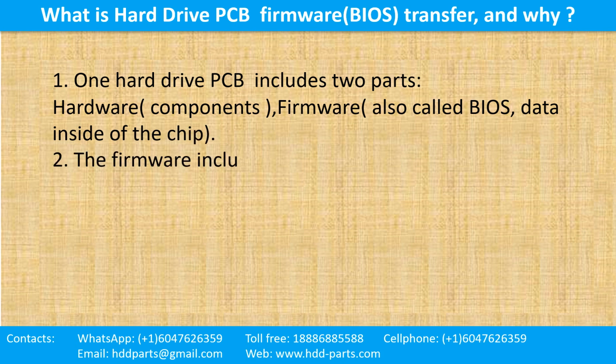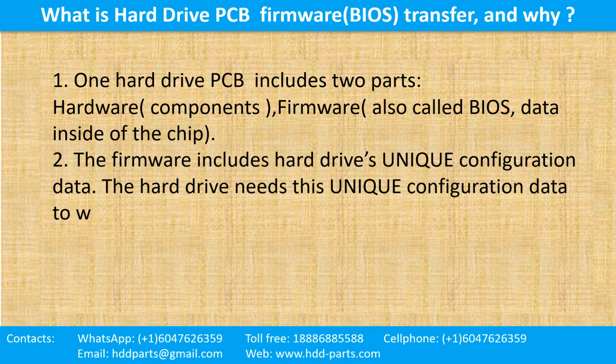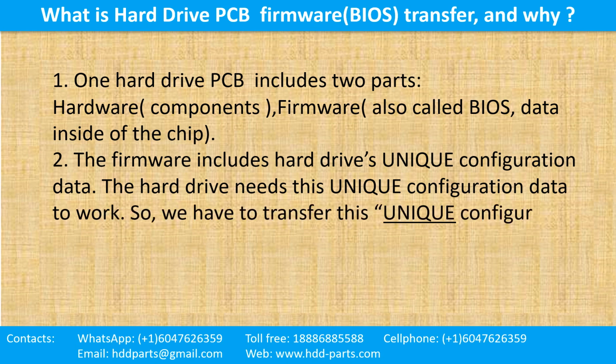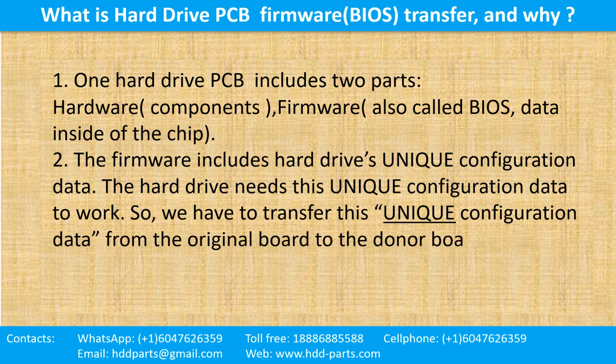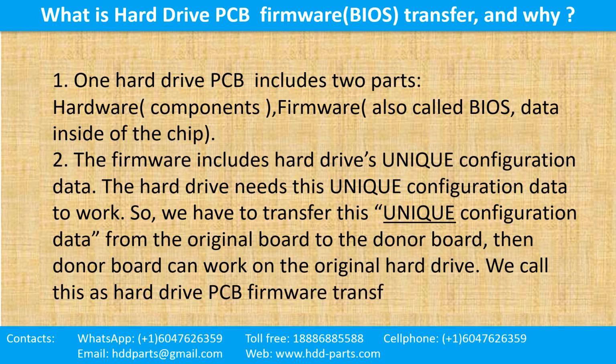The firmware includes the hard drive's unique configuration data. The hard drive needs this unique configuration data to work. So, we have to transfer this unique configuration data from the original board to the donor board. Then the donor board can work on the original hard drive. We call this hard drive printed circuit board firmware transfer.